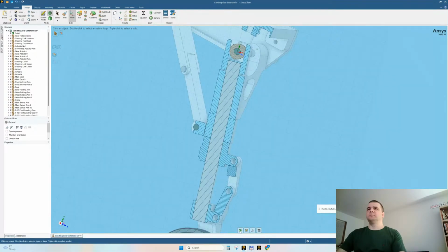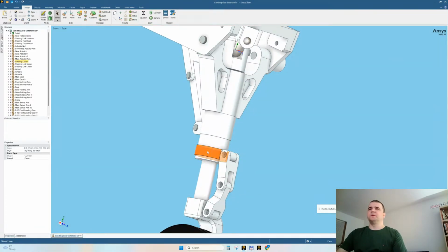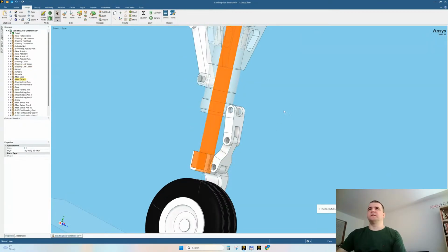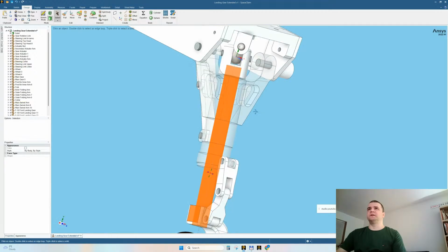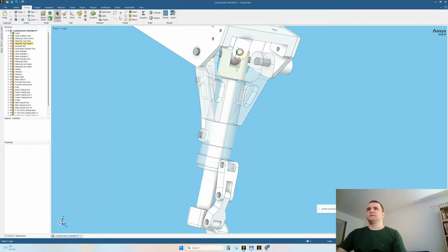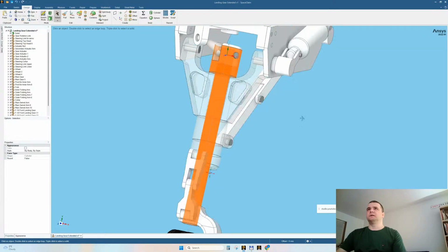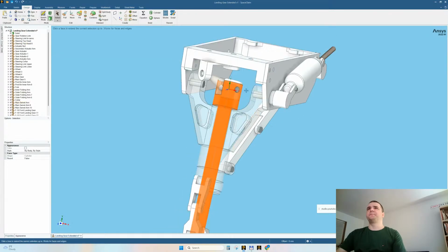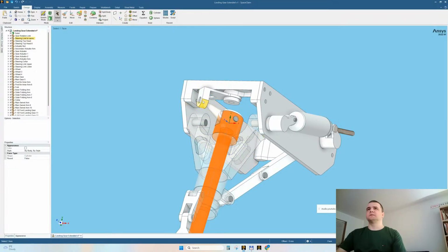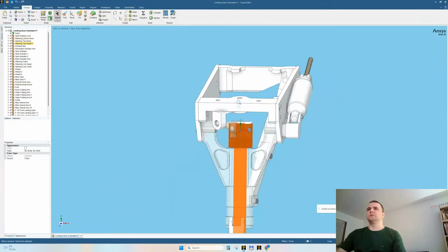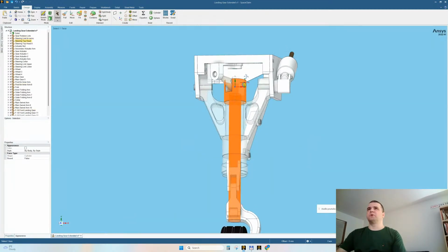Let me come back again for the 3D model. You know, easiest is if we go and maybe say transparent here, and we can understand. We understand now that this part should be fused with this shaft, and this shaft will travel here. If I fuse the shaft with this part, then it will force this spherical joint to work. It will force it. It will move this upward.